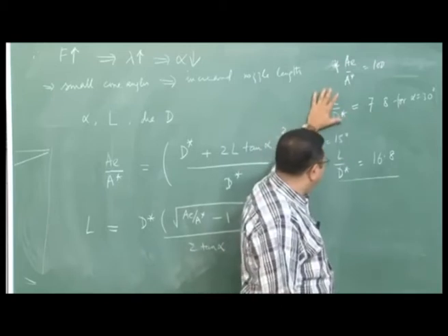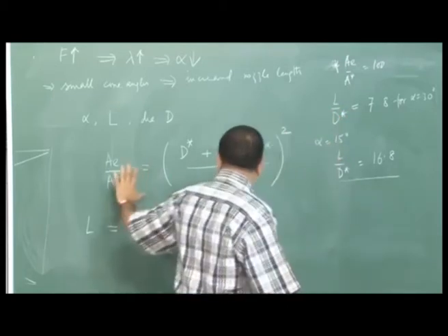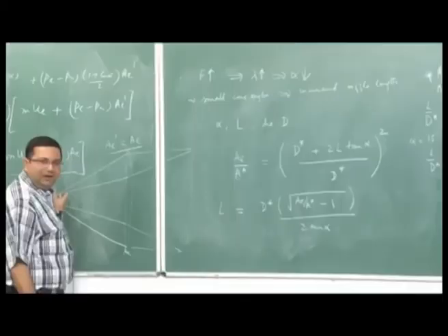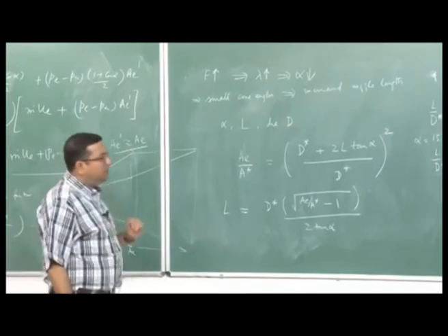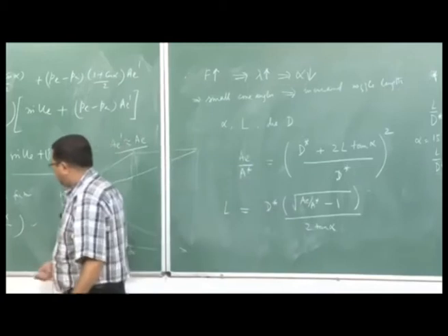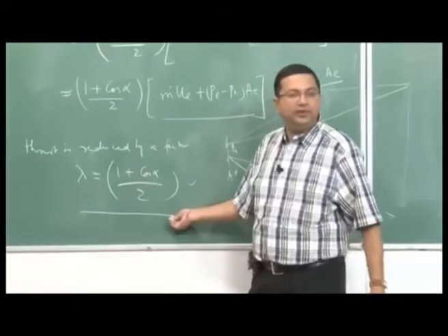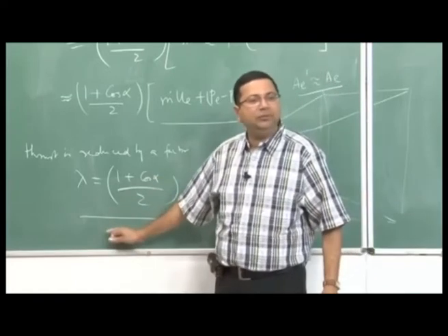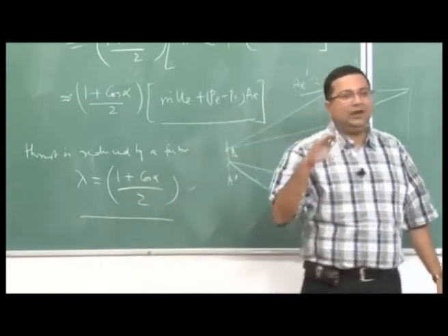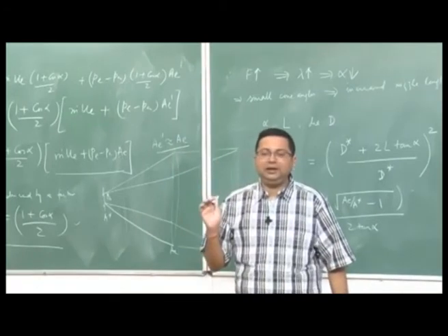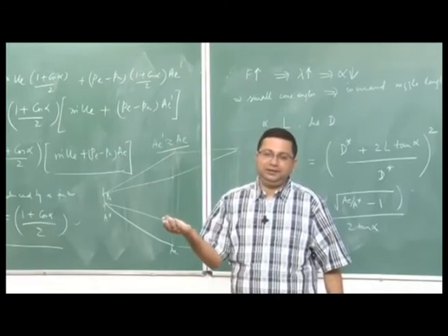So, therefore, what we have shown here is that a conical nozzle, although it is very simple to get the expressions, because of the 3D effect there is a loss in our performance given by this factor. This loss can be minimized by reducing the included half angle, but as we reduce the half angle our length is increasing.